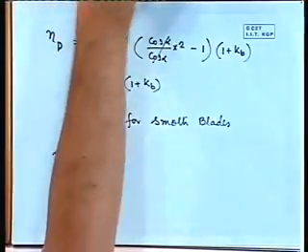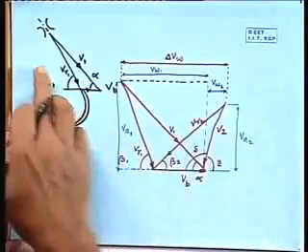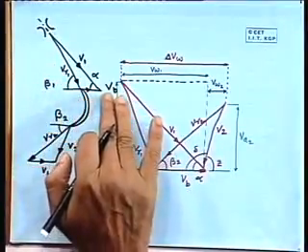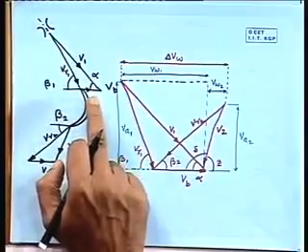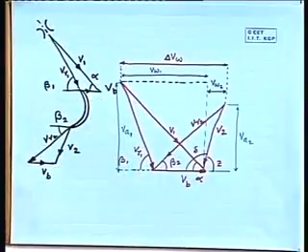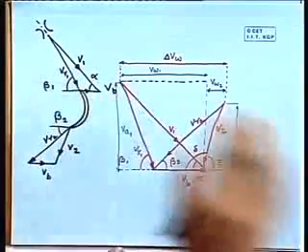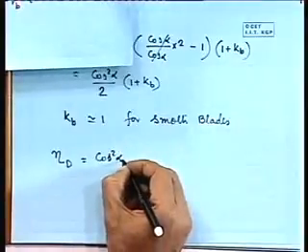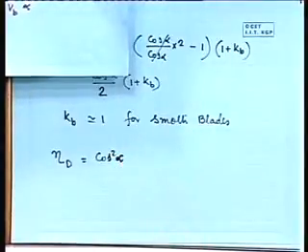Now, let us go back to the diagram. So, you see that efficiency of the blade passage depends on the nozzle angle. So, that is what I told at the beginning, that there are a number of parameters. At the beginning it appears that they are independent of each other. We can select them a bit arbitrarily, but it is not so. We can see that the blade angle determines what will be the efficiency of the turbine.